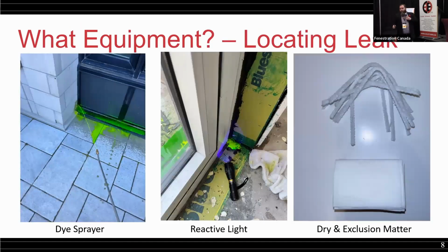The other thing that we find very frustrating is oftentimes what we refer to in the office as fail and walk away. Did it leak? Yes. Okay, my job's done. Bye-bye. I'm out of here. No, thank you. That's not how it works. Find the leak, locate the cause, use some simple tips, tricks, anything you want to do. Again, there's very little standardization, so a team can learn how to do it for themselves, learn different things that work for them, create their own water stops, supplement the caulking, find the holes, actually make sure that it's draining properly, make sure it was clean in the first place.